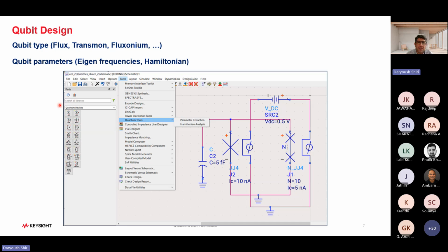You will see in this picture in the schematic, we have a library of quantum devices based on Josephson junction: RF SQUID, DC SQUID, and different connections of Josephson junctions, which are basically nothing but a nonlinear inductor, but it comes in different flavors. In this picture, you will see we have a loop that in one arm there is a big junction, and in one arm there are n smaller junctions.